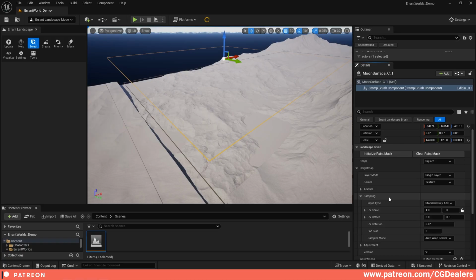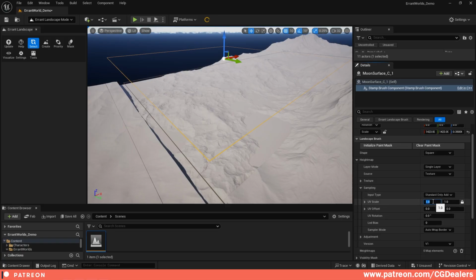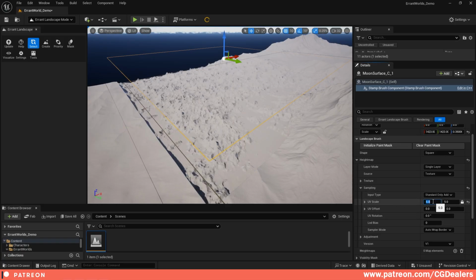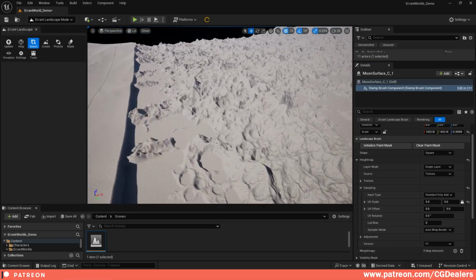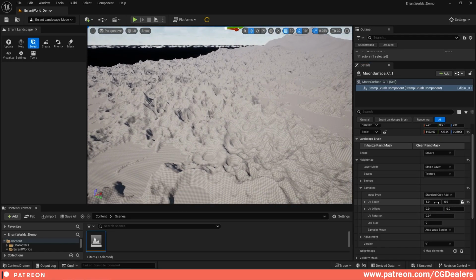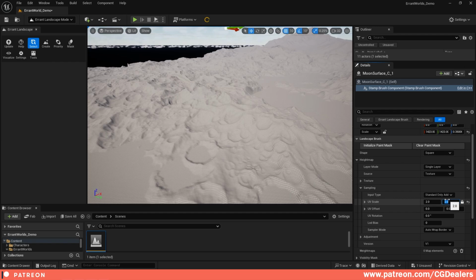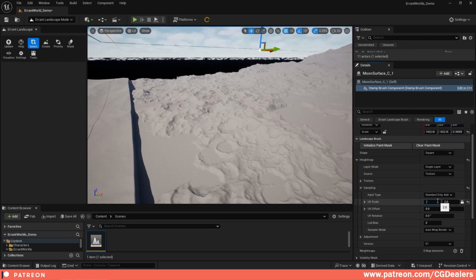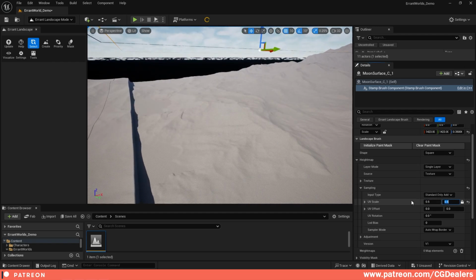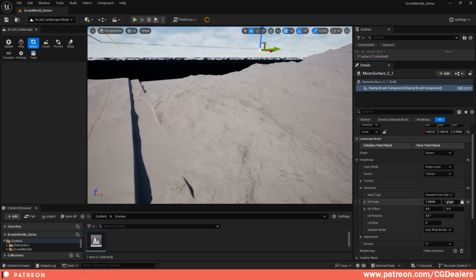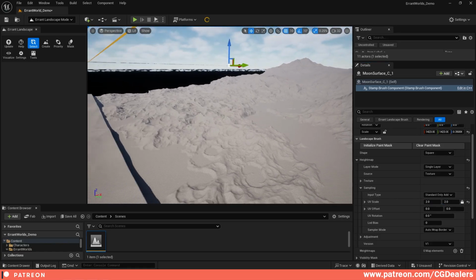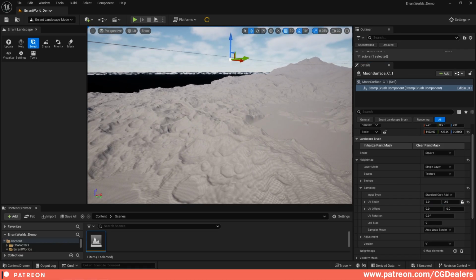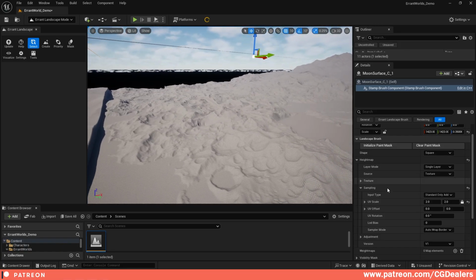If you go to the sampling, you can control the UV scale. Let's do 5. You can see that our crates got dense. Let's say 2, a little less. And if we put 0.5, they got bigger. So I'm going to do 2 per each, so I can have a little bit more detail. So I'm just repeating the UVs over here.